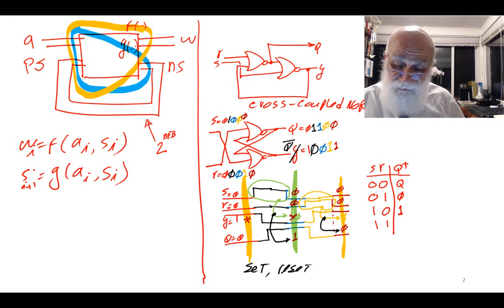And then there is something about this. If I remember how I explained this, I said that Y, the value of Y, is the one that keeps the state of my circuit. Actually, the Q and Y being different, that's how the state of my circuit is kept. If I give my circuit S and R 1, 1, what happens is, if my Q is 0, my Y becomes 0 also. Actually, my circuit forgets whatever it has remembered in the past. And therefore, this is a no-no state for me, or a no-no input for me.